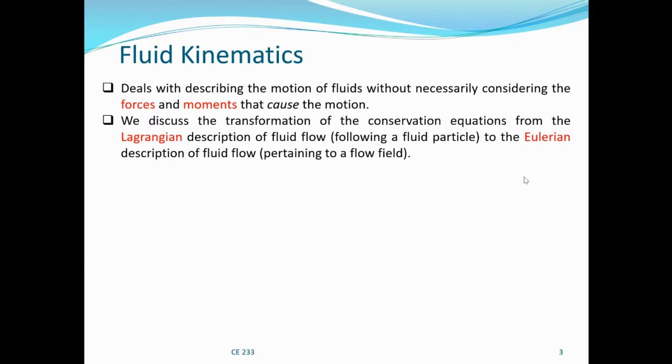While the Eulerian description of fluid flow entails selecting a particular region in space called the control volume. If you remember, I explained the control volume in chapter 2. So we select a control volume and then develop a field, or an equation of flow, within a certain area in space, so that any fluid passing that particular point in space should have that property.